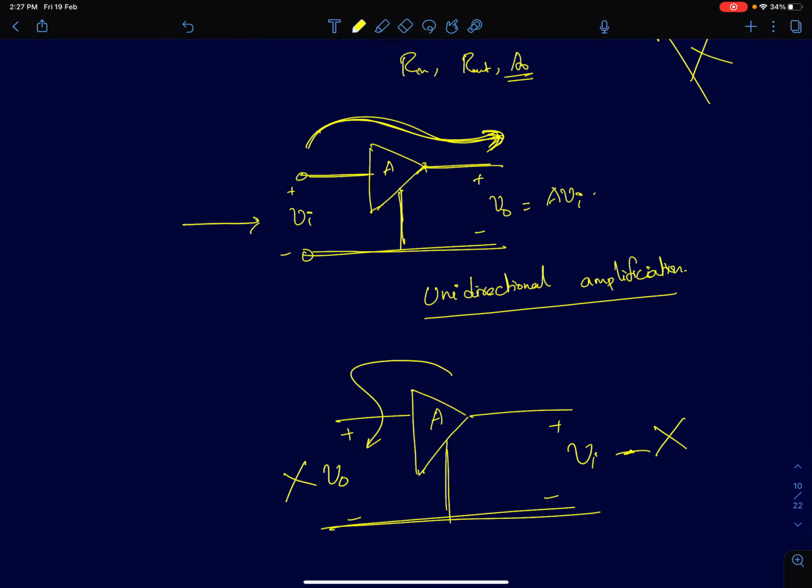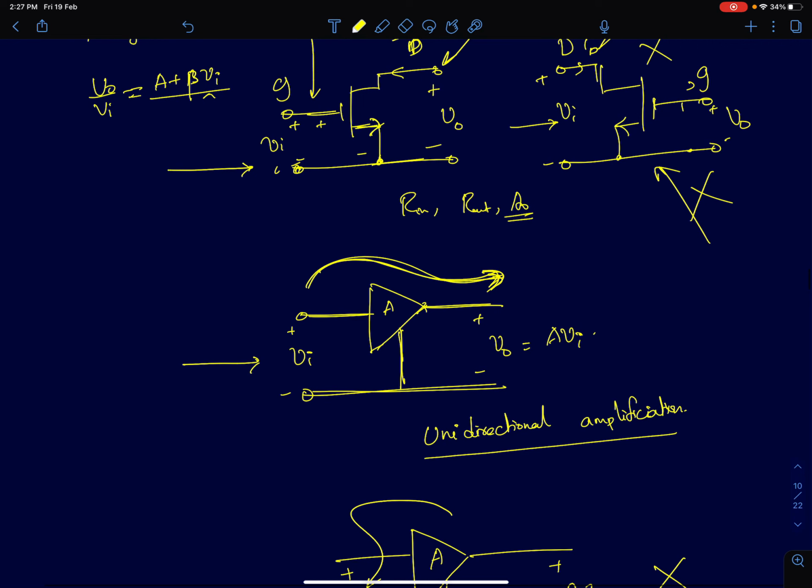Okay. So now I have introduced very basics of common source amplifier. The next thing that we are going to do for an amplifier is to find out the important parameters of an amplifier. Those important parameters are the input resistance, Rin, the output resistance, and the intrinsic gain of an amplifier. These parameters help us in deriving a small signal model for this amplifier. From that small signal model, we can very accurately predict the total voltage gain that this amplifier can offer under loaded conditions. When I say loaded conditions, source has a finite source resistance and there is a finite load resistance.